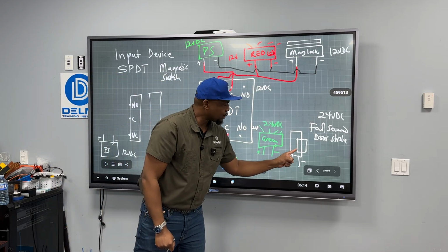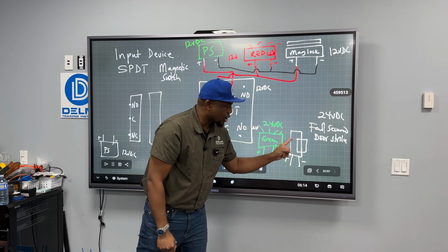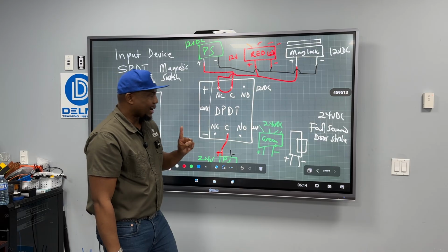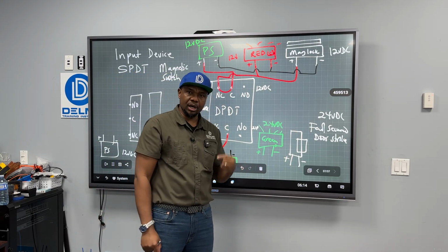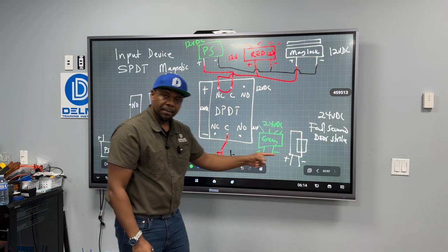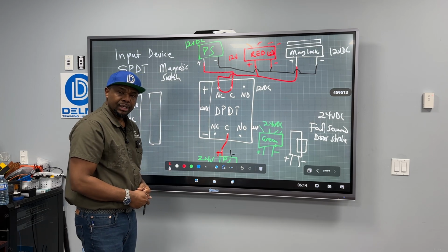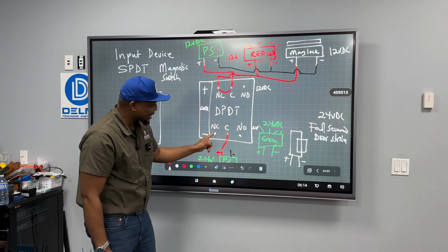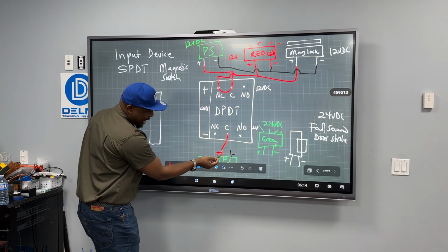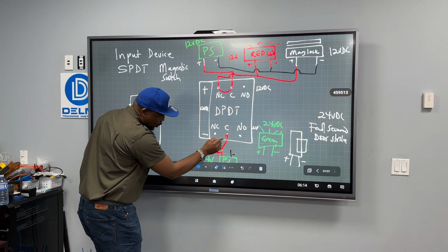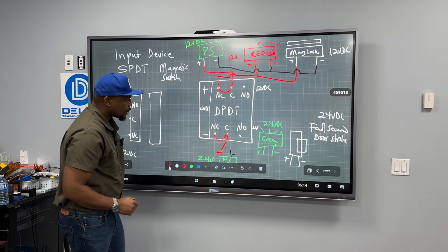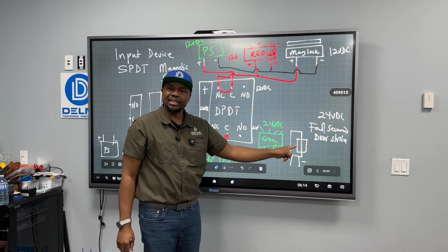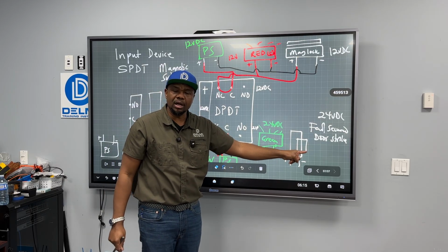The way the electromechanical door strike works is this. When I send power to it, it unlocks. If there's no power, it stays locked. So if I want this to unlock, and I connect it directly here, because you know when I bring the positive here, this automatically comes here. So what is going to happen if I connect this here? Right away, this is going to get power, and this is going to stay unlocked.